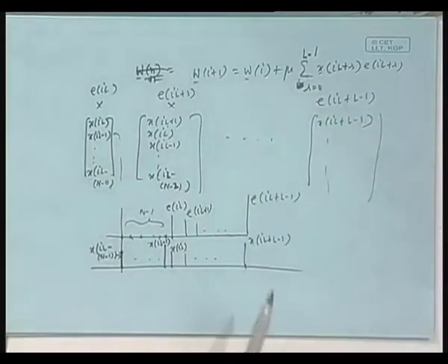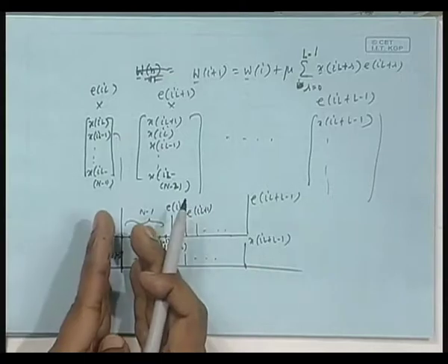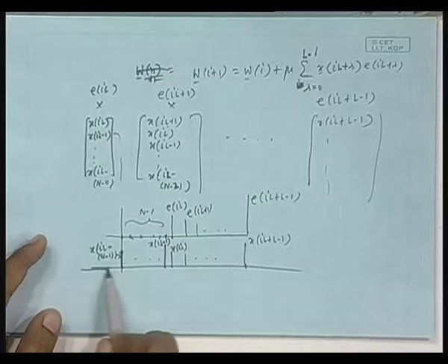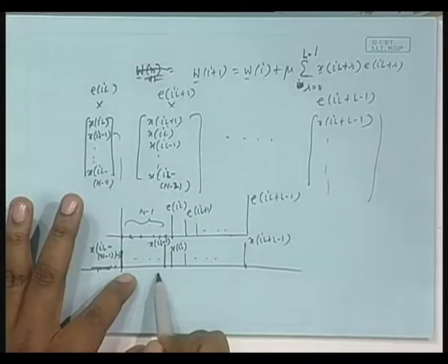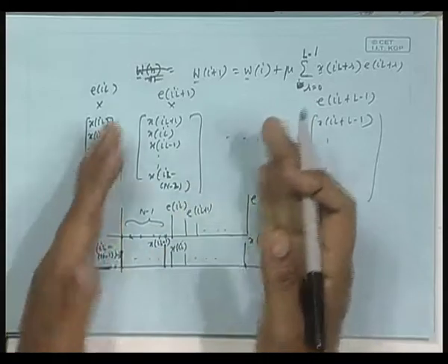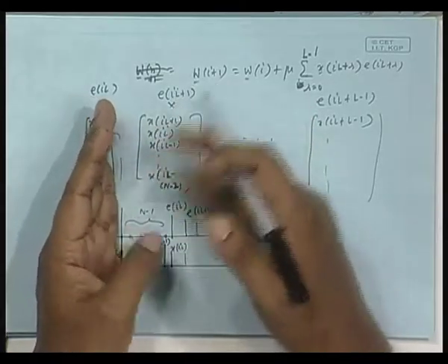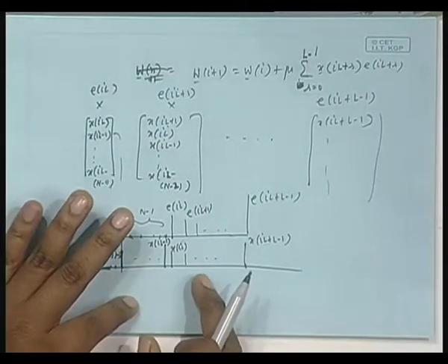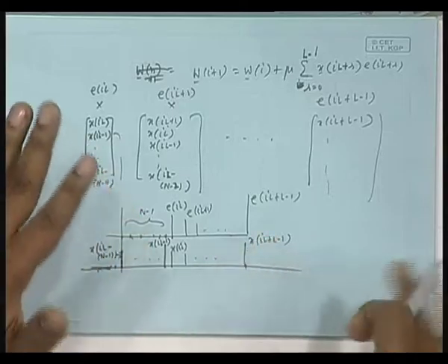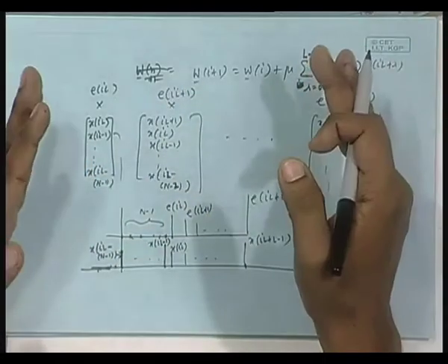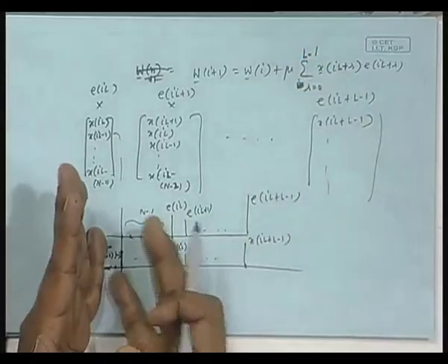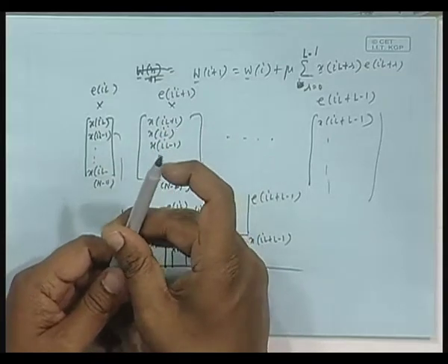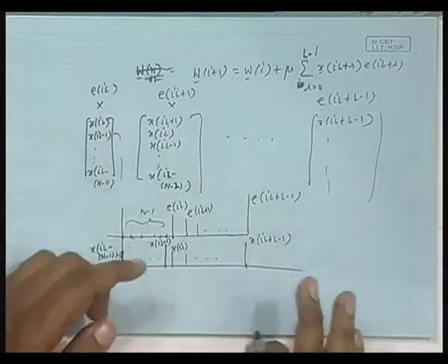For the second entry, what will we have to do? If I shift the entire thing to the right by 1 bit and send in a 0, as though there are zeros here, and then within this zone I multiply top to bottom and add, will I not get it? So, it is like that intermediate step of the graphical way of circular convolution, when you have reversed it and then shift and chop off. So, if this is the reverse version, what is the original version? You understand? I have to use the circular convolution. Are you following me?